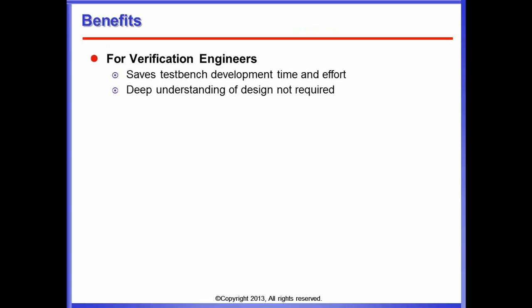So what that means is you cannot take this based on assumptions. You take a pretty high risk in getting an unstable design as soon as the reset scheme changes, as soon as the ratios of the clocks change, as soon as the offset of the clocks change.